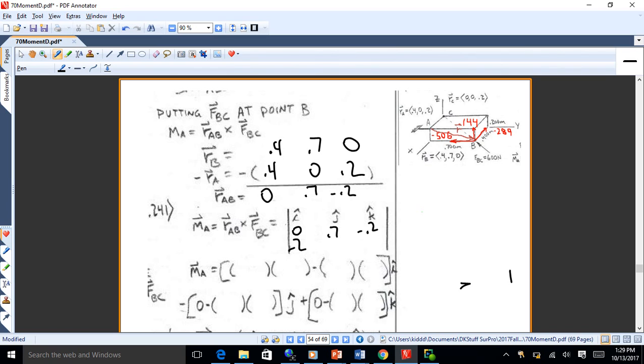Okay? And then the other thing is it's a regular position vector. The length of it matters and should stay in the term, because the longer that moment arm is, the bigger the moment. So you want to keep the length of that vector in there. So you do not unitize R. You just leave it as R. Okay. And then you just do the cross product, and you can do that however you learned it. As long as you do it in a reasonable way and get to the right answer, we're good.